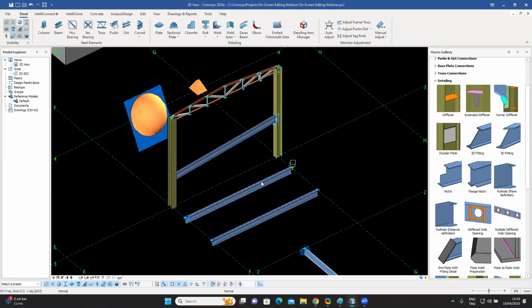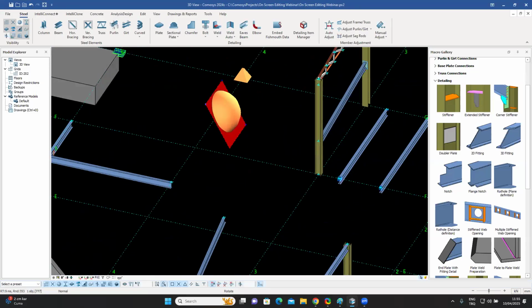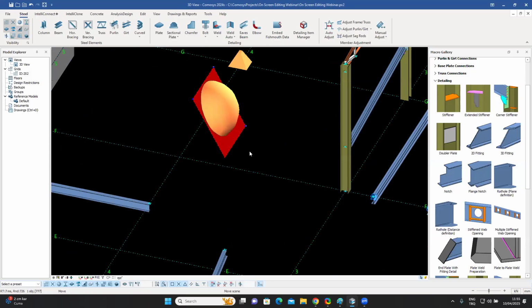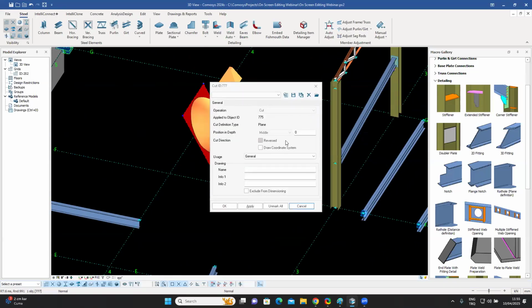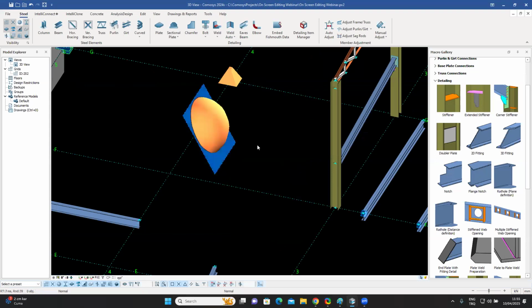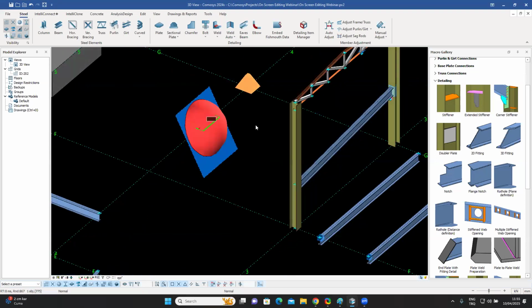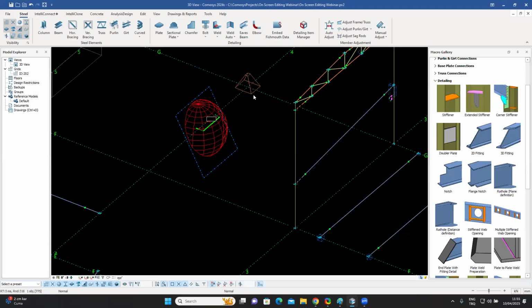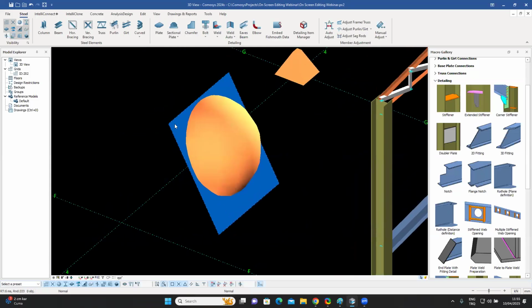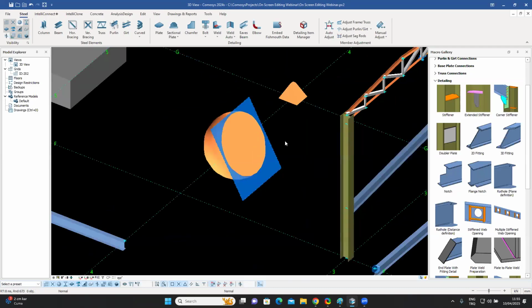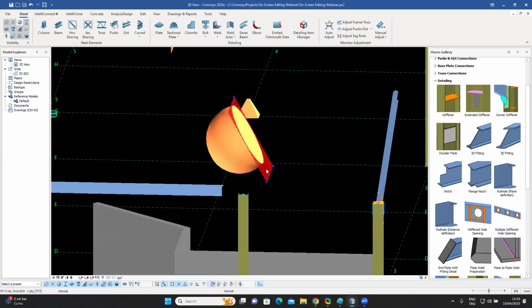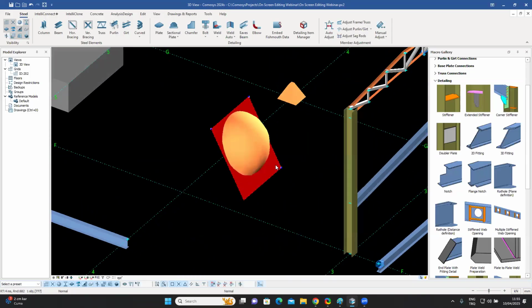The plain cut, which is a different cut, as you remember, this is a new cut which was added in the last version. This one, now, as you remember, it had the option of being reversed. So it would basically cut any object. Like basically, it's cut a sphere right now, and it's cut the sphere according to a plane over here. Now, what I can do is if I select this cut and if I press Control Q, it will reverse the cut. As you can see on the screen, pressing the Control Q button will reverse the direction. So it's a quick, fast way of modifying it.